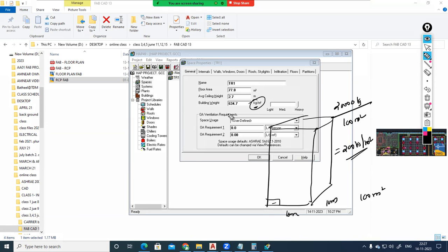So that's why if your building is not bulky, the wall thickness, everything is less, suddenly it will heat up. Suddenly it will be ejecting to the surroundings. Suddenly it will cool. If your building is bulky, slowly only the heat will be entering inside. Initially the wall material will prevent it, but slowly only it will become cool. It will take some time because it will be holding a lot of heat.